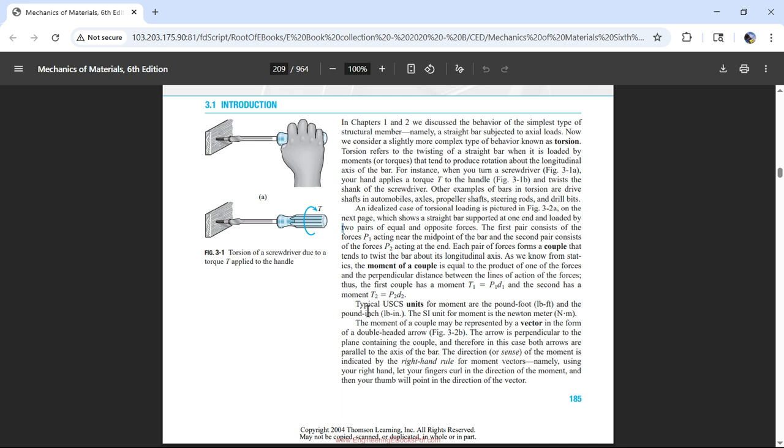It'll take more strength to actually stretch it, and what do they call that? Well, there's two different things. At the yield point, you get perfect plasticity, where the second it starts to stretch, it's going to take the same amount to keep stretching it. But then you get those molecules to rearrange, and that's called hardening. And so you do get strength hardening. A ski edge, when it hits hard ice or rocks, but anyway, it's hardening of the steel.